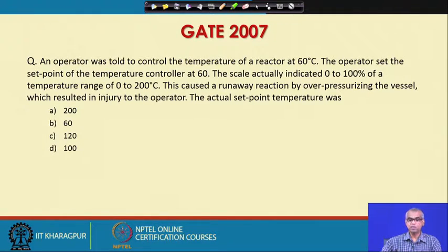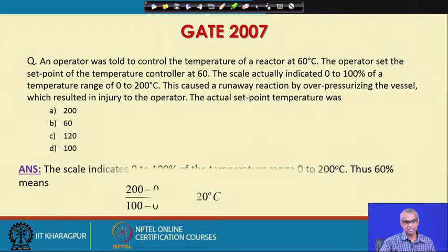The actual set point temperature was 60% in the range 0 to 200 degrees Celsius. So, that will be 120 degrees Celsius.